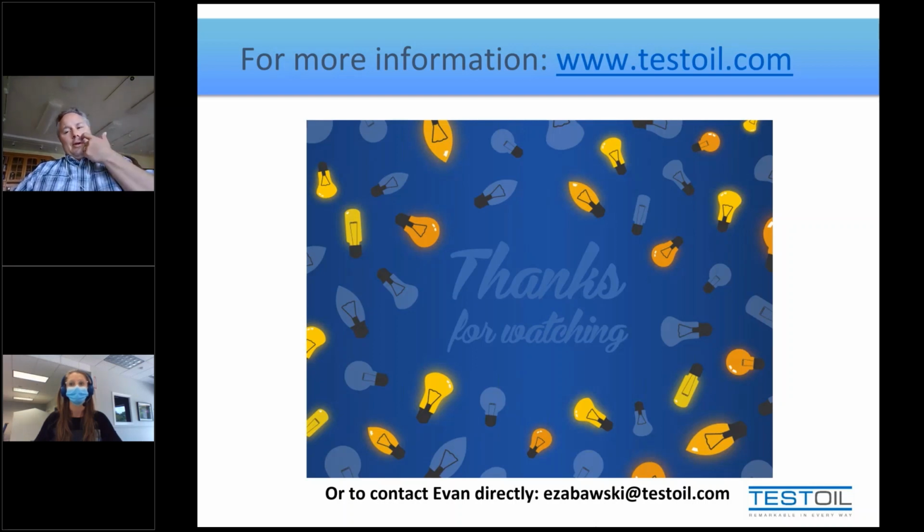To degas a sample on site, meaning the person who takes the sample degasses it, really the only easy way is to leave the cap off. And when I say off, I don't mean completely removed, sitting on the table. I just mean loose so that it's not sealed. If you let it sit for a couple of days, eventually most of the gas will evacuate and you'll have less of an issue. You can also ask labs to degas it, whereby we use sonication and vacuum to help remove those gases.